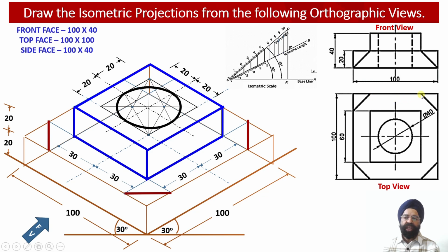1, 2, 3, 4, 5, 6, 7, 8 points can be located, but we can see 7th and 8th point we are not able to see in the isometric projection over here, because this portion of the lower web has been covered by element number 2. So these three inclined portions corresponding to the horizontal web number 1 we have to plot over here.